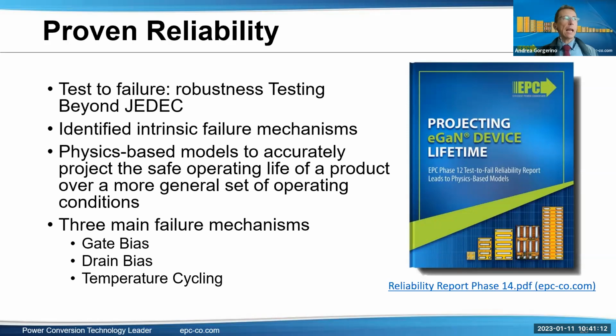So we have found that with proper design techniques, which means proper layout techniques mainly, we can have extremely clean waveforms. This is one of the advantages of GaN FETs. They're very linear. They have extremely low parasitics, especially all of our packages, very low common source inductance, which really allows us to have very clean waveforms during switching events, which reduces the ringing.